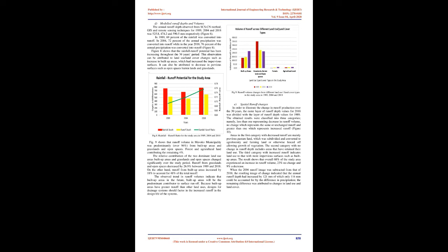In the curve number map for 2004, CN value 86 and CN value 100 were dominant. The observation was attributed to 47.6% coverage of the watershed by grasslands and open spaces which have a CN value of 86 and 17.9% of the watershed being covered by rivers and water bodies whose curve number value is 100,